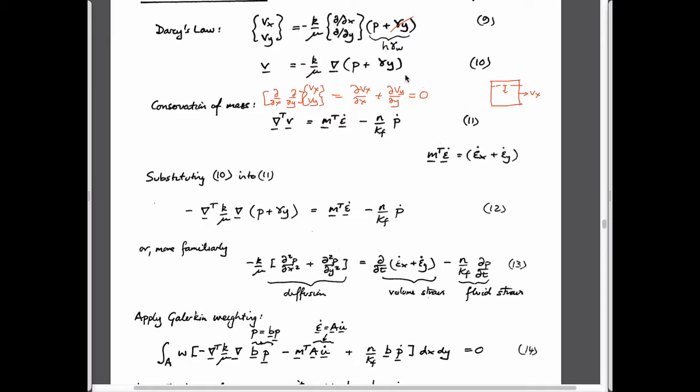So this expression is just saying that if you pull it out in the x direction, the top has to come down for it to be fully conserved. In other words, the fluid volume that comes out of here, if you want no volume change, incompressible flow, then you have to have the same change in volume of the control volume, or the same amount of fluid has to come through the top. So this is a conservation of mass, actually conservation of volume as it's written. If we multiplied everything by density, it would be conservation of mass.